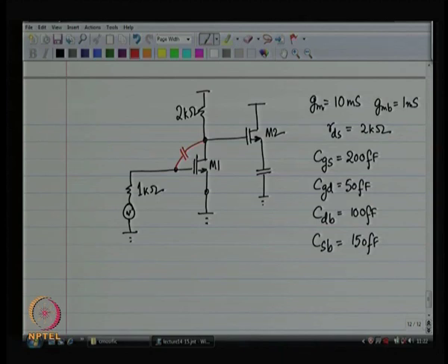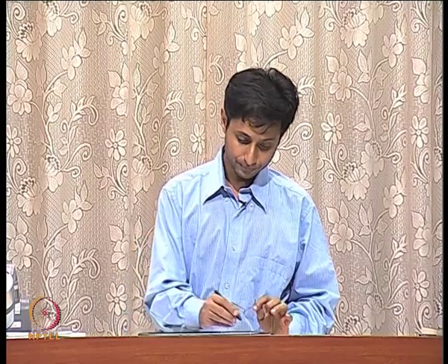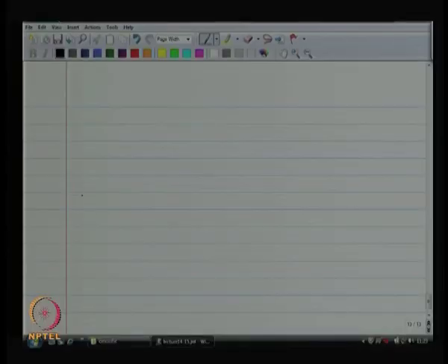So, how do you fix problems with the Miller effect? What is the commonly used strategy? You use a cascode, right. A cascode or a common gate structure after the common source structure is what is going to fix the Miller effect problem. So, instead of my second cut design, what I would do is something like this.